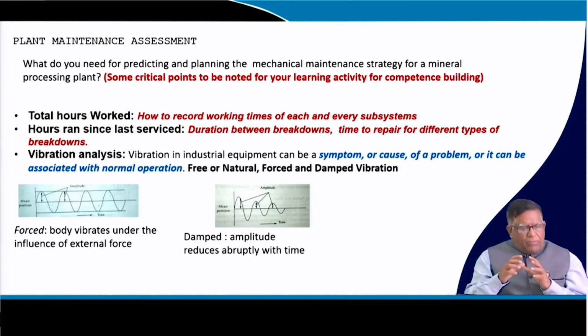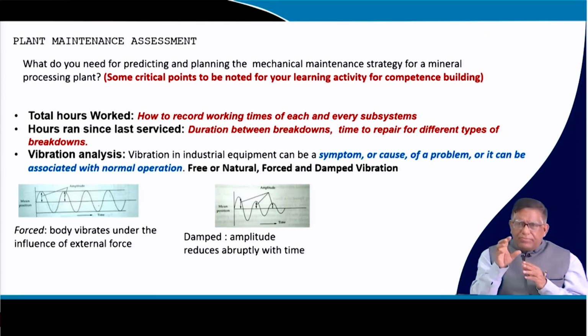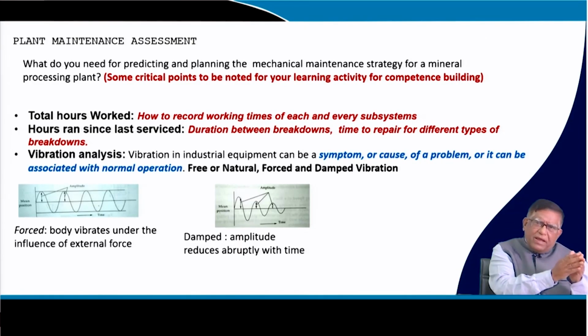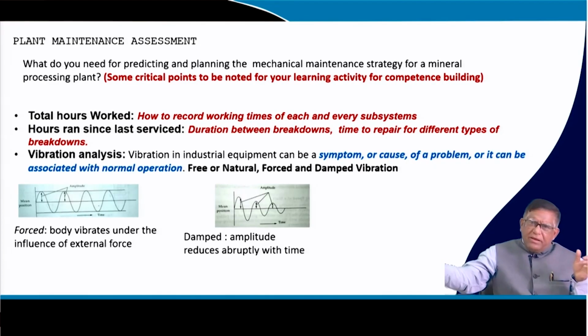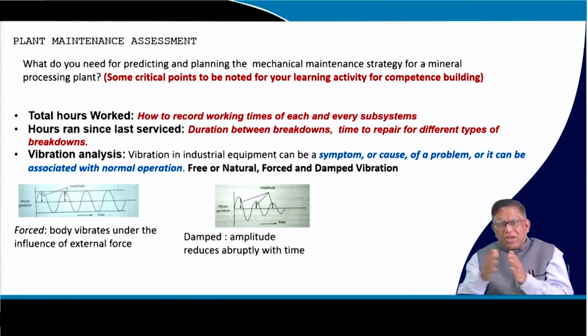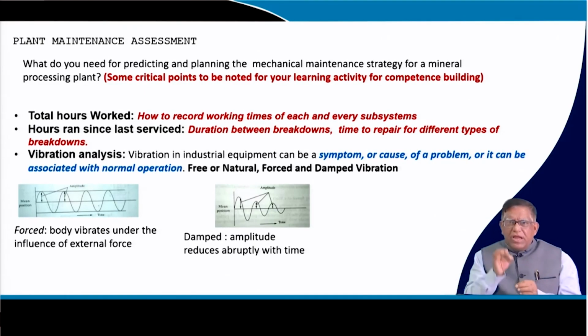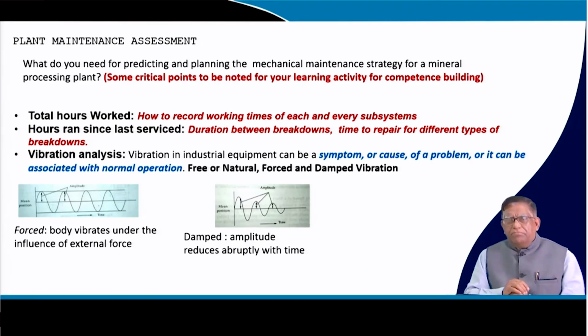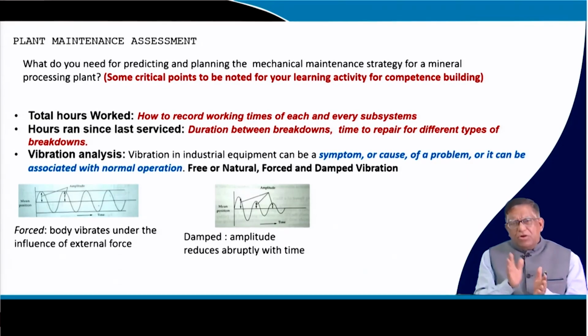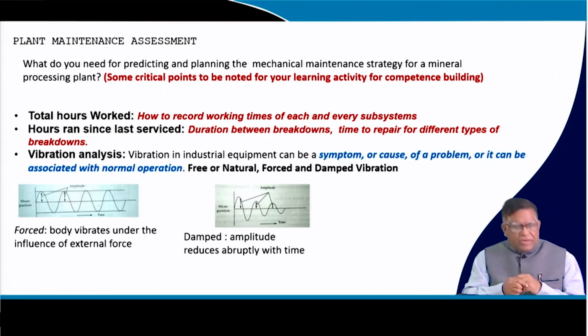Then you will have to monitor how many hours since last service. That means I have done a repair, and after that, sometime later, it has failed; how much time has it taken from this time to that time? If the time between two repairs is very long, that means you are doing a good job. But if you repaired yesterday, today it failed again, tomorrow it failed again, the time between failures is getting very short, which means your maintenance is not proper. So you will have to find out such data, and from that you can take a maintenance decision.